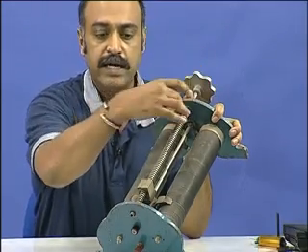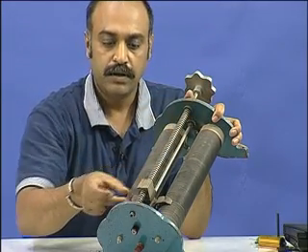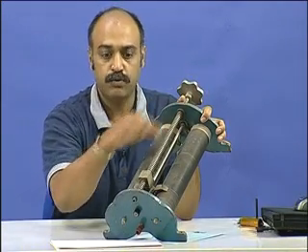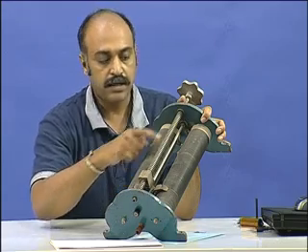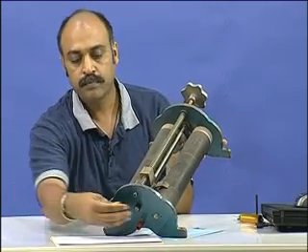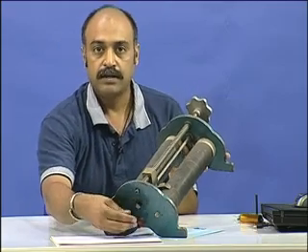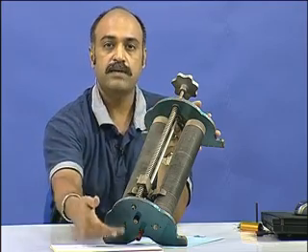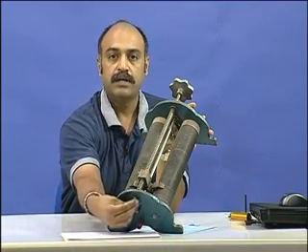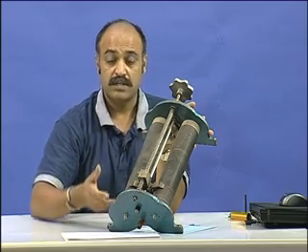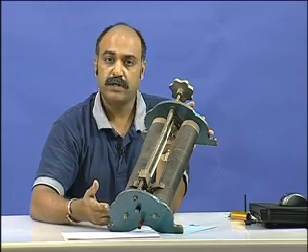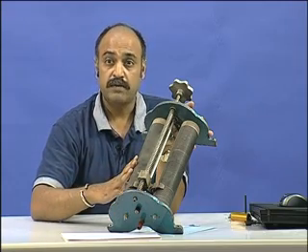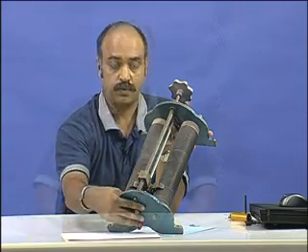Now, there is a lead screw arrangement here with a center tap which can move around. I can vary this knob here and therefore change the position of the center tap. The center tap is connected to this knob here. The one extreme terminal is here, the other extreme terminal is on this side, and therefore you have the 2 extreme terminals and the third center tap terminal here. So, this is also a potentiometer, but in the high power regions of operation, these types of resistors are called rheostats. You can also get fixed resistors of such high powers.